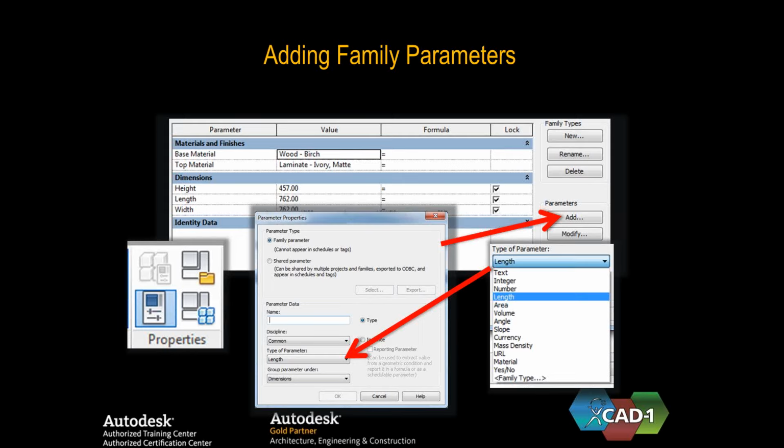Maybe you're going to do an area that says for every 200 square feet, add a desk. Well, if I have 300 square feet, I don't want 1.5 desks. I either want 1 desk or 2 desks. So I'd use an integer that would determine, am I rounding up to get that next desk, or do I round down? You want whole numbers for those. And if you don't care about whole numbers or half numbers, you can just use a number.